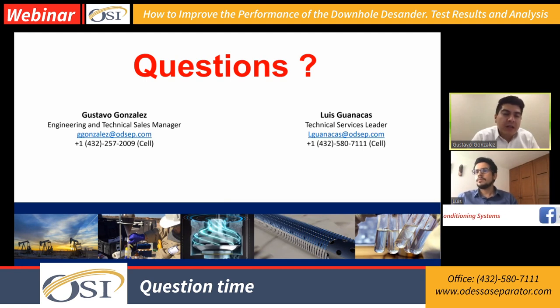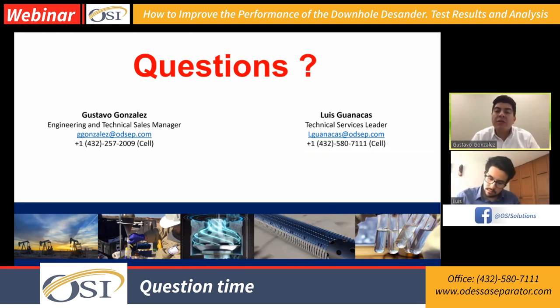Another question that we have is, can one helix fit all the production ranges? I think, as we discussed in the webinar, one helix cannot fit all the ranges, due to the centrifugal force that is generated around, plus the linear acceleration for the particles. And I will answer more like, can one of your ESPs produce either 5,000 barrels per day or 350? No, it can't. The reason is that the ranges you already have for the motors or the stages of your system are going to generate a lower efficiency if you're depleting the well like that.